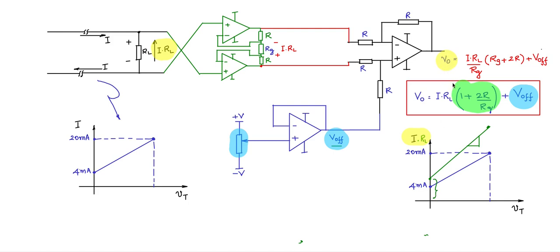So V0 here can be made to take this form of relationship, the red line, from 0 to some value, and this could be the VT versus V0 line ultimately on the receiving side, and this is what can go to the anti-alias filter, Sallen-Key filter, and from the output of the Sallen-Key filter can go to the A to D and into the digital domain.